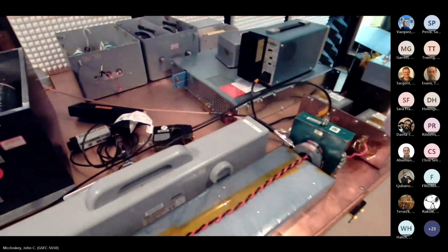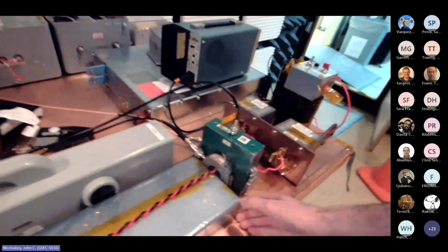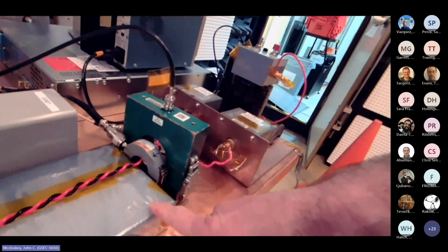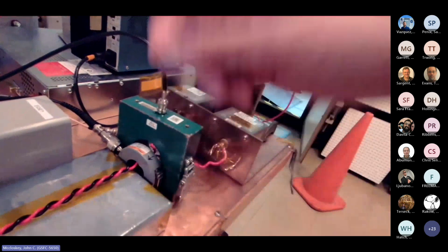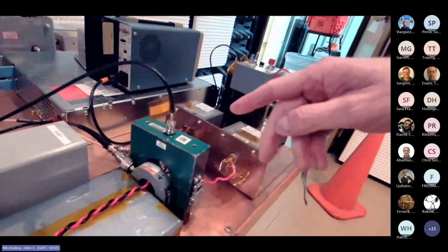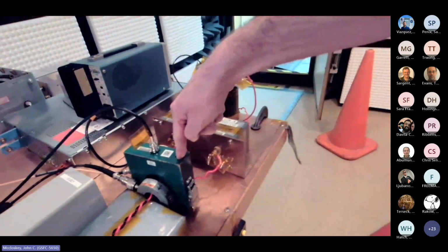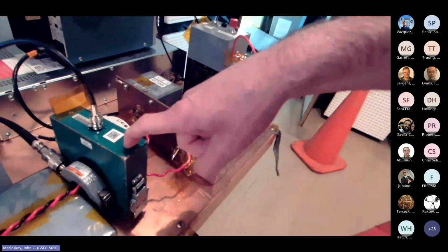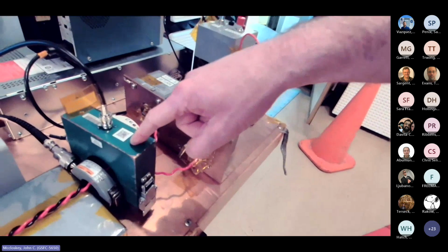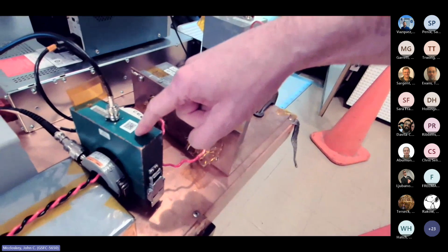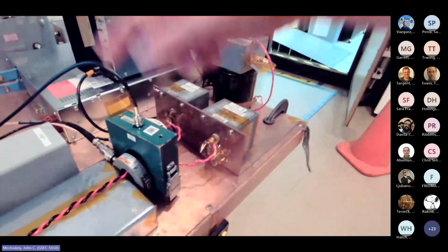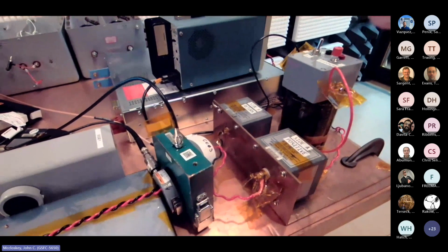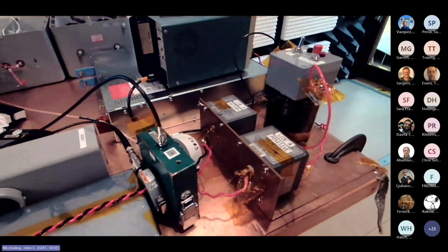Now, but all is not lost. When you use these other types of current probe, more of a standard type current probe that we typically use in the frequency domain, you can still do that, but you want to pay attention to whether it has a flat frequency response in the frequency range of interest. This probe here is a Pearson 3525. I don't want to sound like I'm doing commercials or anything, but Pearson just makes really good current probes. And a lot of them, like this one included, were made to measure things like lightning strikes, and specifically in the time domain.